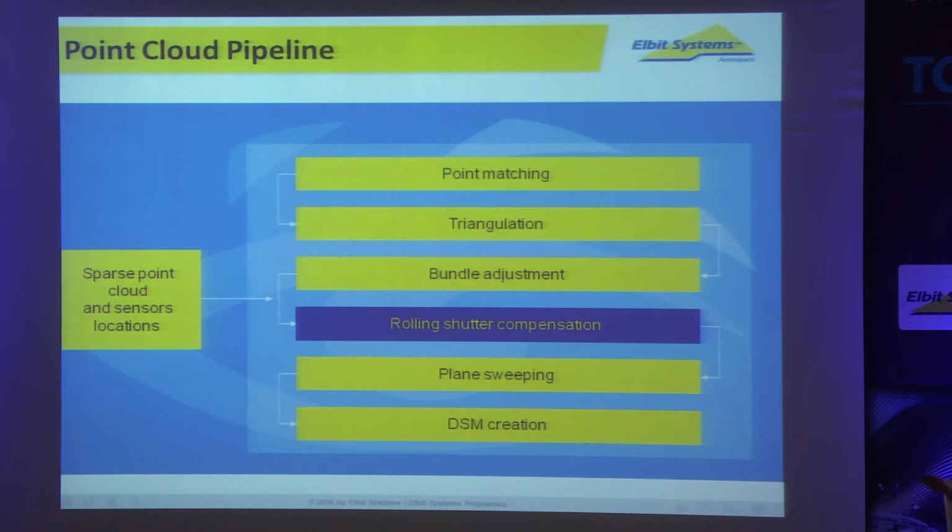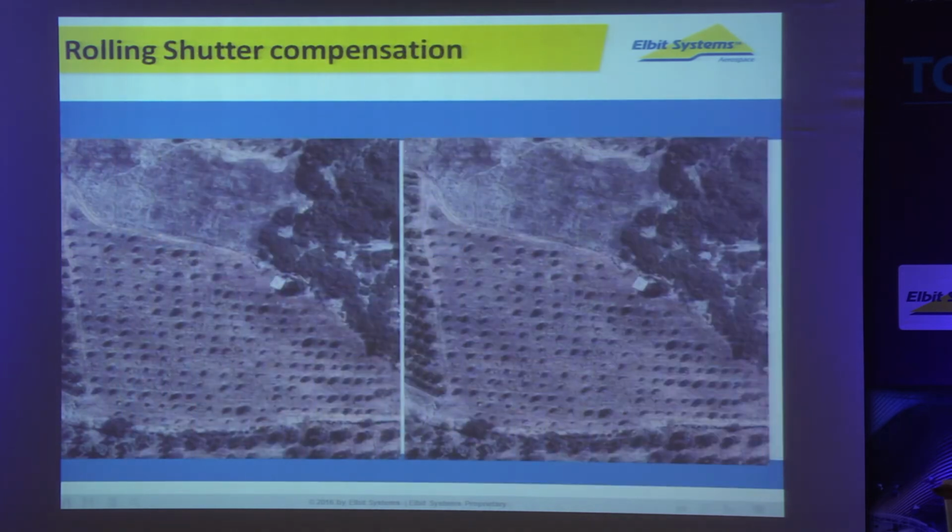Weren't very good to start with because we have a rolling shutter effect. So this is an image I really wanted to work, but we couldn't manage to make it work. But what we should be seeing here is a wobbly effect of the images because our camera is a rolling shutter camera, which means we have an array of sensors which are exposed consecutively. And we have those in our mobile phones, but in our case, the camera is mounted on an aircraft which has very high frequency vibrations, and also our rolling shutter is pretty long. So we have this effect,